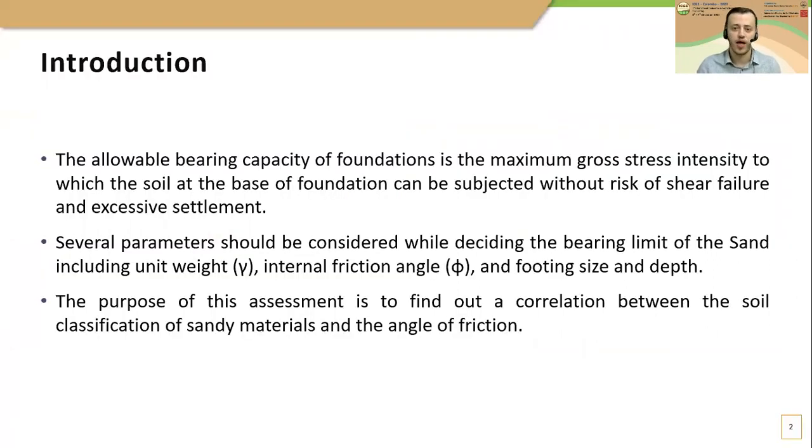To start with, the allowable bearing capacity of foundation is the maximum gross stress intensity to which the soil at the base of foundation can be subjected without risk of shear failure and excessive settlement. As everybody knows, several parameters should be considered while deciding the bearing limit of the sand, including the unit weight, internal friction angle, and foundation size and depth.